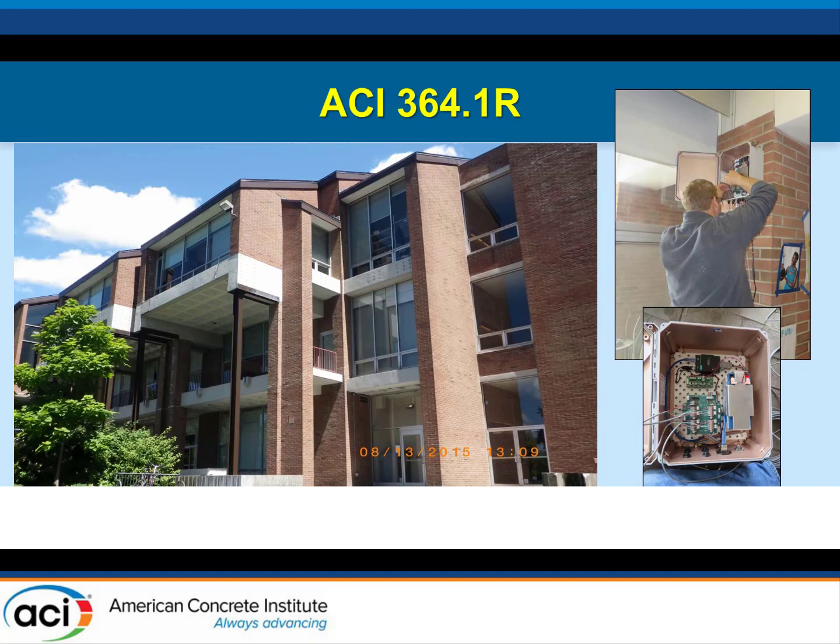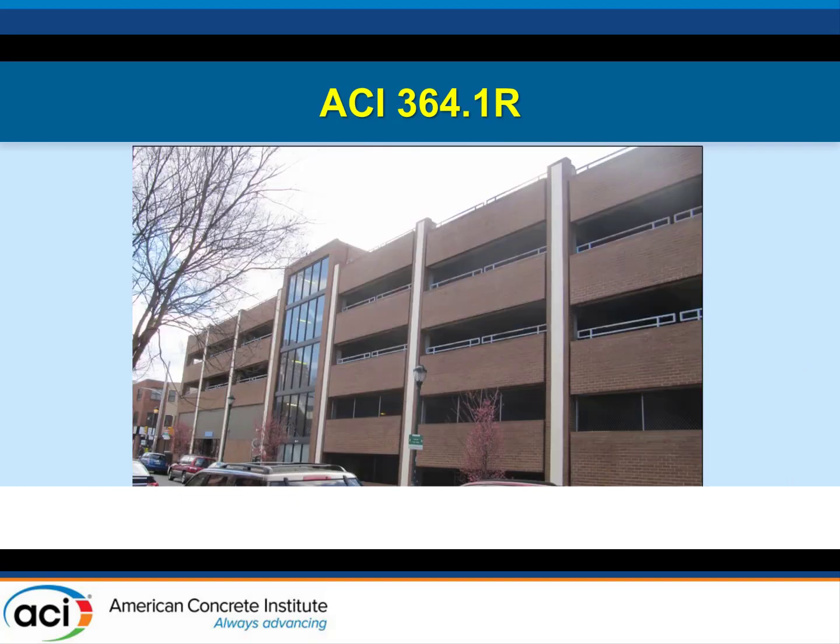On the right-hand side, you see what we did was we went in and installed strain gauges and data loggers and a monitoring system so we could just record over time what was happening to the structure. Basically, we're still looking at it today. I think there's about another 5 years left to go in the owner's schedule, at least the schedule that we talked about, when the building gets taken out of service and replaced, but we'll see.